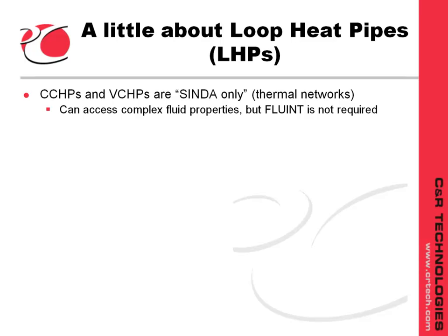But there's another class of devices that's being used more and more, loop heat pipes, or LHPs. It's too much to try to describe loop heat pipes here, so I just wanted to make two key points. First, they're very different from traditional counterflow pipes, both in their design and analysis. The second point is that Thermal Desktop and FloCAD have the capability to design and simulate them as well.